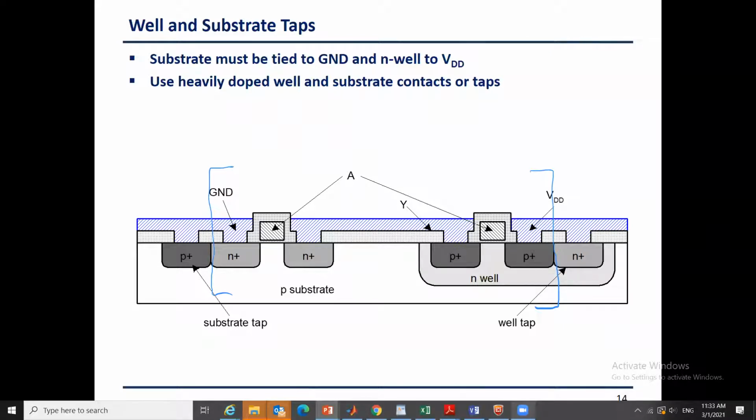Here I have a P+ that is connecting ground to the main substrate. This is the body, okay, and it's a shared body for all NMOSes. So where is this connecting? This is P material, this is P+, as if he is creating a connection to where? To ground. So he is connecting the body to ground. So he is connecting here the body to ground. The same in the PMOS. Okay, the same in the PMOS.